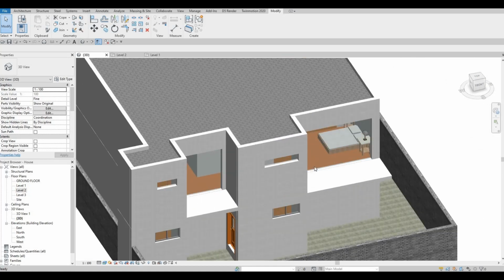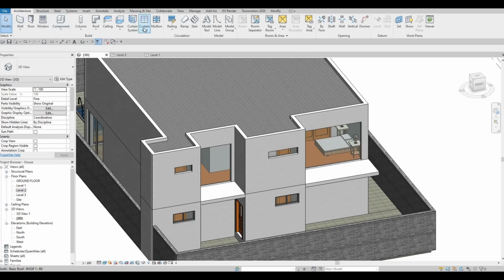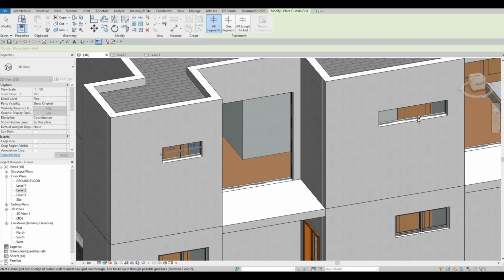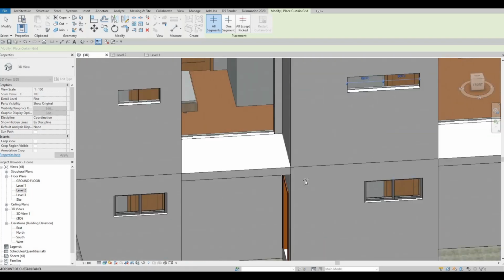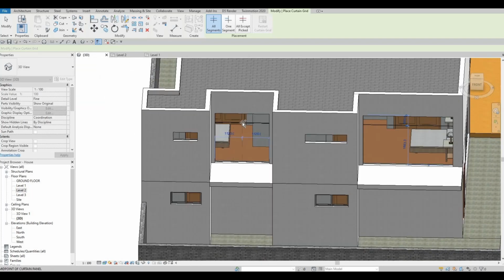And then definitely we need to add the mullions, but before that, let's put in curtain grid. Here we just want it in the middle so that it looks similar to the bottom, that it's being opened separately. And then here what I like to do is add 500 at the top first, and then go into midpoint and see how much we do.